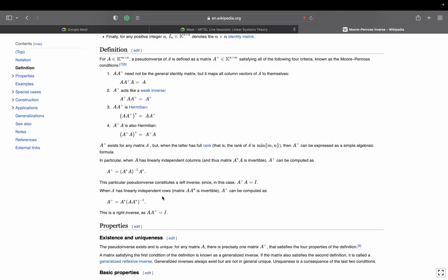So that is my pseudo inverse. Okay. So now how do I find the A matrix? V sigma inverse U transpose. Okay. So that's my A matrix now, just using data. So if I want to estimate the state matrix from data, in estimation theory, you can use this. Now the thing is, the sensor data might have unnecessary information which we don't need to estimate.